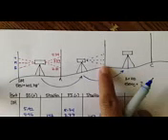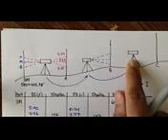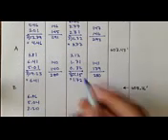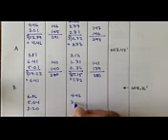So you're at this point and you're backsighting to B, and you read the top, middle, and bottom. And you get these numbers. For the foresight, you're at this instrument and you foresight to C, and you read the top, middle, and bottom for those. You get 4.46, 2.62, 0.79.